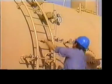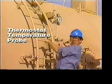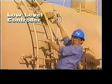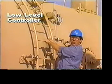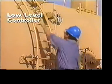Now over here, we find the thermometer, which indicates treating temperature, and the thermostat temperature probe, which maintains the desired treating temperature. Here's the low-level controller, a safety device installed on the treater to ensure that the fire tubes are always covered with liquid. This prevents the fire tubes from overheating.